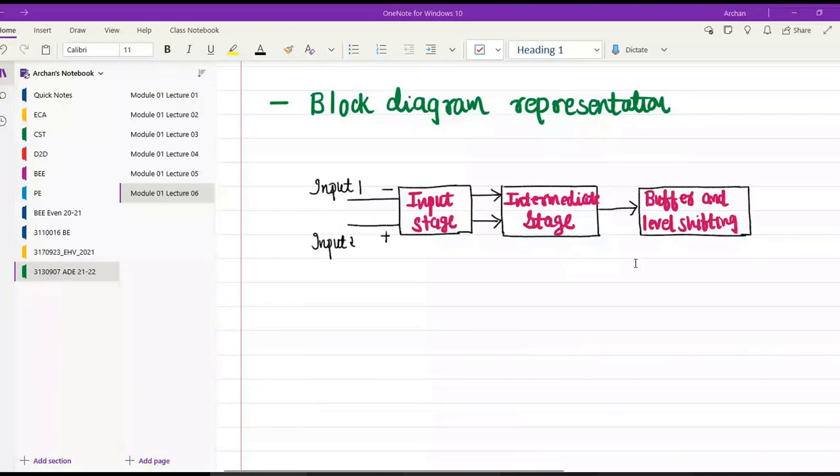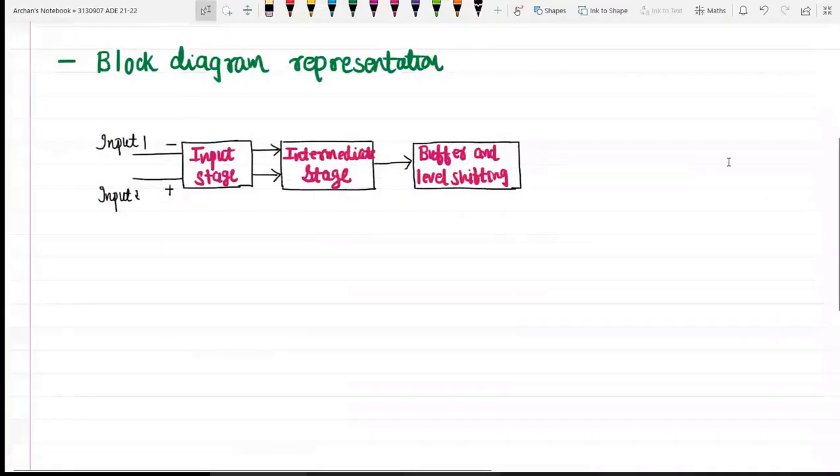Okay, so we were talking about this level shifting stage, right? Whenever we talk about the DC quiescent voltage level, that will be applied as the input to the next stage. Hence, stage by stage the DC level increases well above the ground potential, and such a high DC voltage level may drive the transistor into saturation. This further may cause some distortion in the output due to clipping, and this may limit the maximum AC output voltage swing without any distortion.